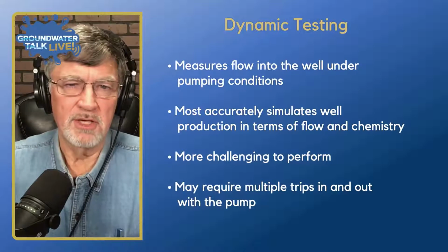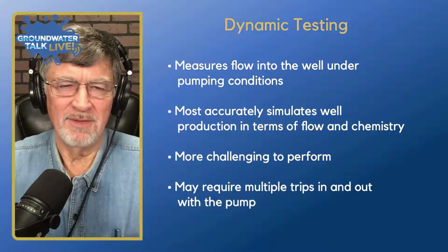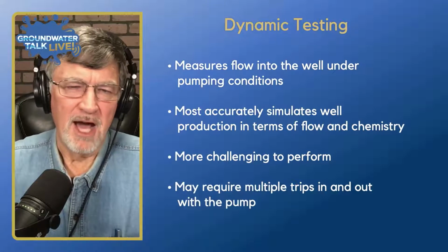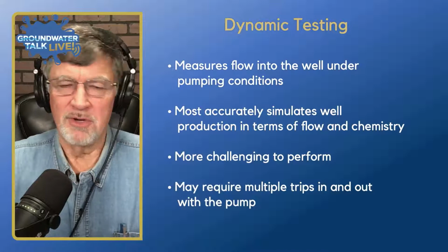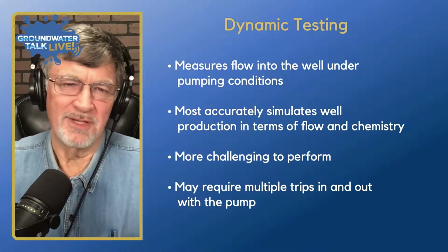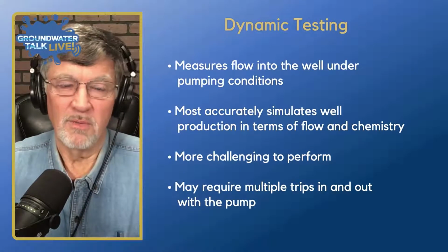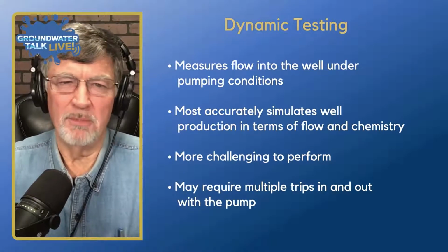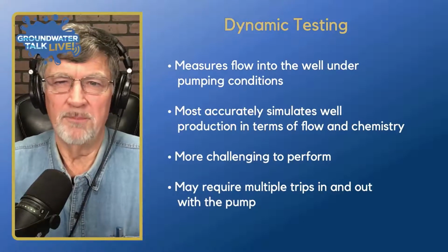So with dye trace, sometimes you can do it with the pump, leaving the pump in, but not always. Sometimes it's hard to thread it down there. So even though they say they can always do that, my experience has been that it's 50-50 on that. So where it works, it's great. Where otherwise you're pulling the pump and doing the exact same thing you would for an EM flow meter.